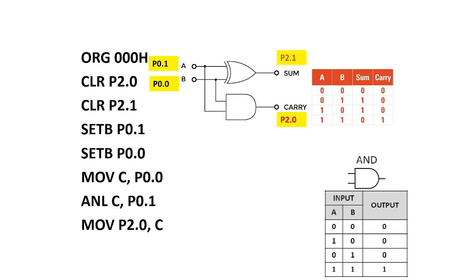First, in parallel I will put the table for your better understanding. This is the first instruction of the program. First we need to clear the bit port 2.0 and set it to 0. That means port 2.0 will be 0, right? Similarly, the third instruction clears the bit port 2.1 and sets it to 0. That means port 2.1 also will be 0, right?